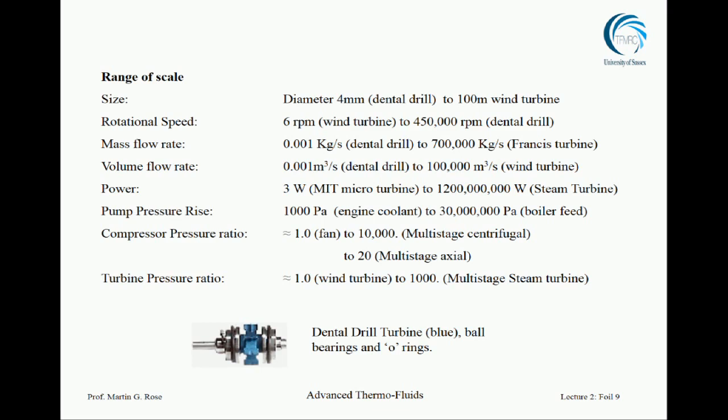The opposite end is a thing called a boiler feed pump, and this was one of the main products of Mather and Platt when I worked for them, so it's particularly interesting to me. About 300 atmospheres of pressure to force water into a boiler. So boiler feed pumps, they'll have about 7 or 8 stages. They're turning at about 3,000 RPM, and they're generating that pressure.